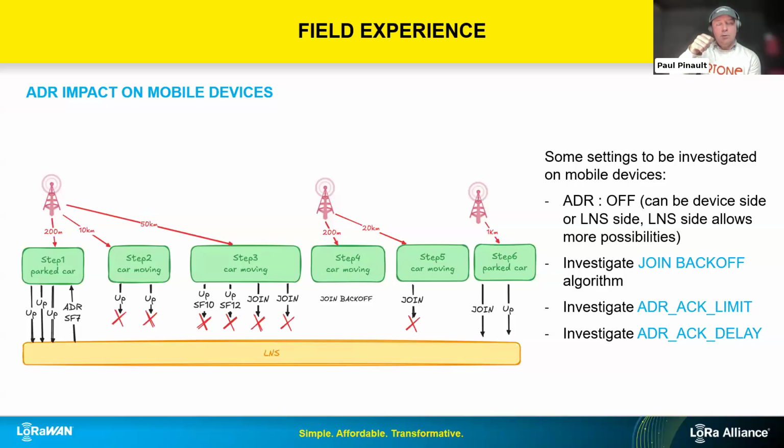And as we have seen, there is the join backoff procedure. The first tries of the two joins in my step 3 are about 10 minutes apart, so we try to join fast, basically, but there is no network at this place. After that we go into the backoff process, which can be like 0.01%, and so it means we only have one try to join per day.